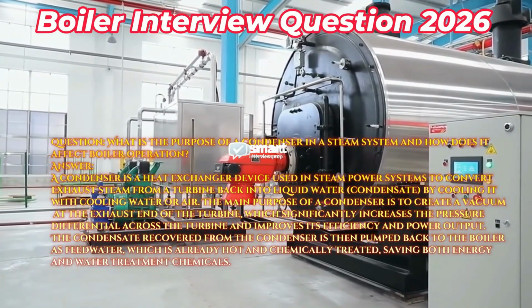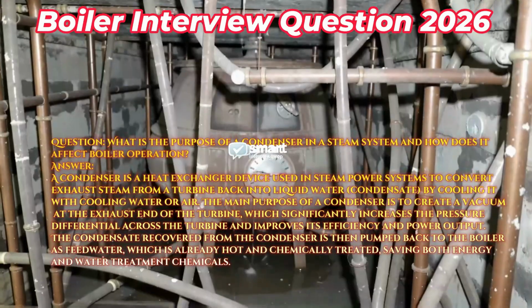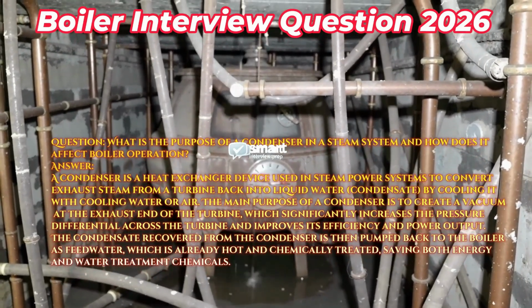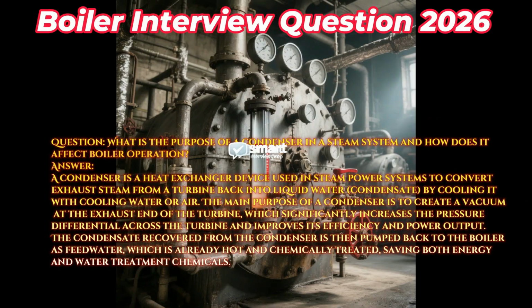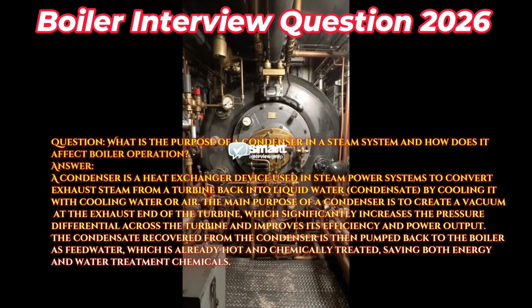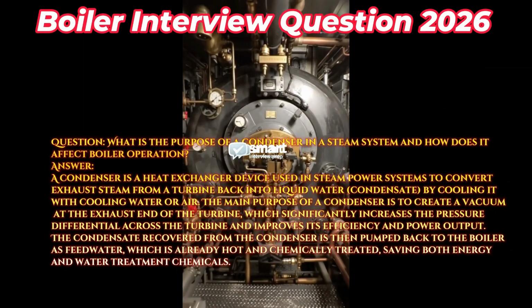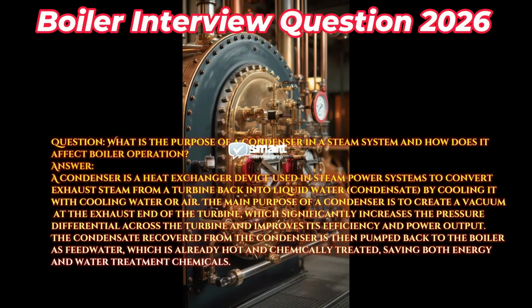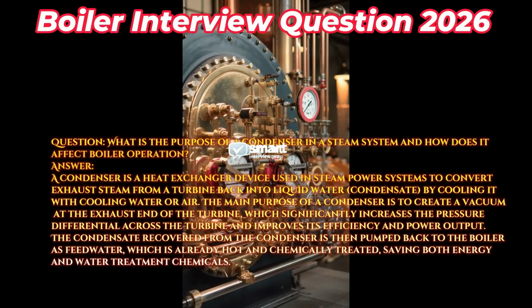The main purpose of a condenser is to create a vacuum at the exhaust end of the turbine, which significantly increases the pressure differential across the turbine and improves its efficiency and power output. The condensate recovered from the condenser is then pumped back to the boiler as feed water, which is already hot and chemically treated, saving both energy and water treatment chemicals.